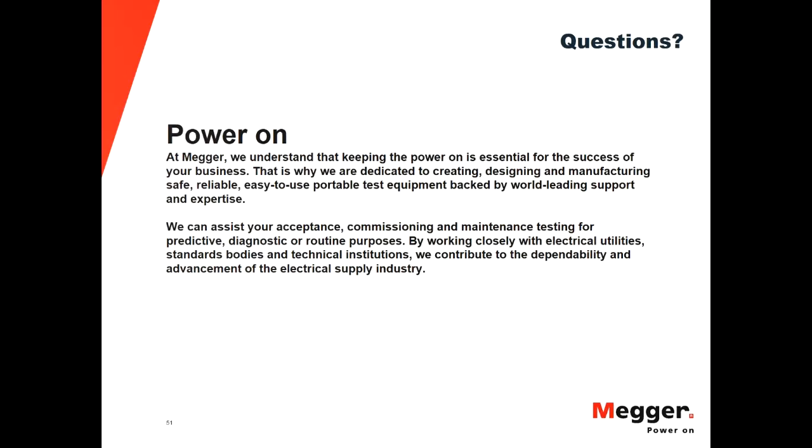A battery that is not charged at the right voltage might be affected by that condition. So you can accelerate one of the failure modes, which is positive plate corrosion, if the battery is overcharged or floating at a higher voltage than recommended. Or you can also accelerate the sulfation failure mode, which is the condition of a battery that is undercharged.